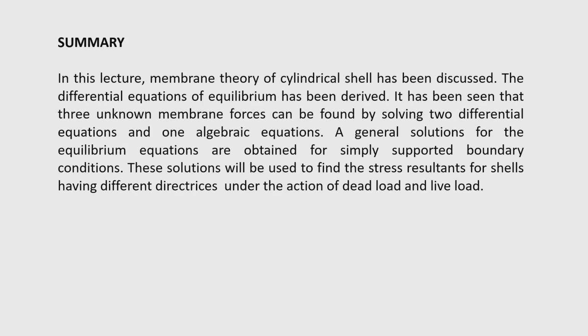The required quantities are the radius of curvature and the values of x, y and z. After giving this input, we can derive the expression for membrane forces in the cylindrical shell for any type of directrix. There is no restriction that it should be a circular cylindrical shell or a paraboloid shell; for any type of directrix, this expression can be used.